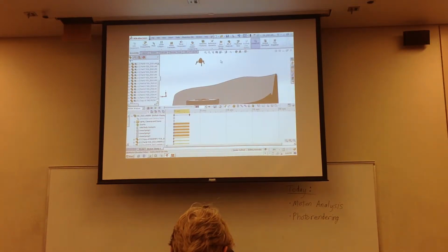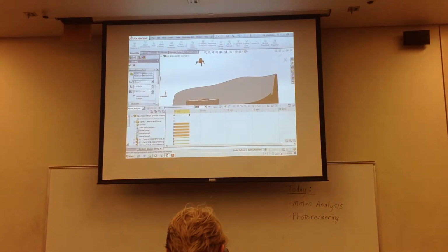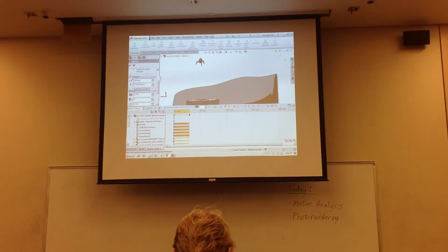Spring creates force proportional to displacement. A damper or shock absorber creates force that is proportional to velocity. And if we look at the way it was defined, you can see that in the units itself, like this coefficient C has, I put in a value of 0.05, but its units are pounds force per inch per second. So the faster this thing hits, the greater the force that is dissipated. Okay?